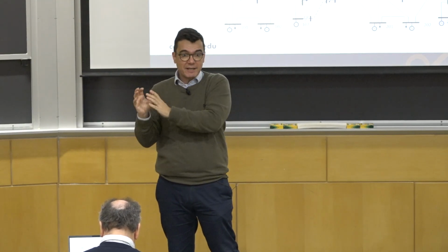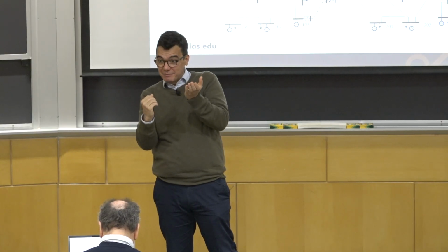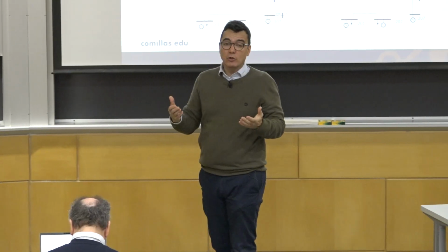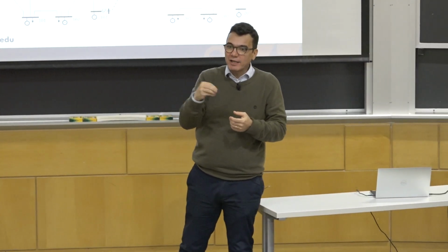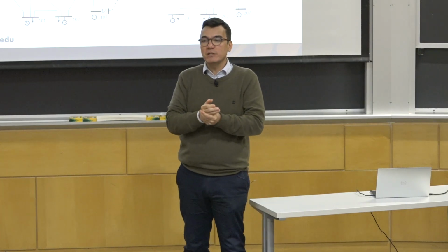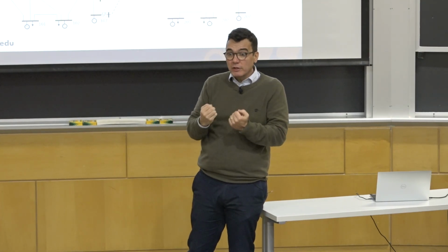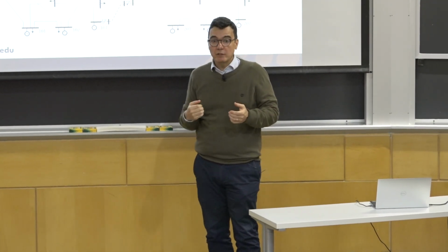So the product is the same, but the current is much lower, okay? The lower the current is, the lower the losses, because whenever you have a current, which is nothing else than the number of electric charges per time unit, you have losses by the Joule effect. So the lower the current, the better, because you're transmitting the same power, but with lower losses.